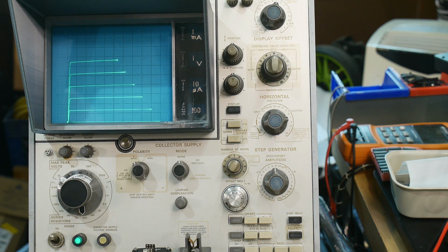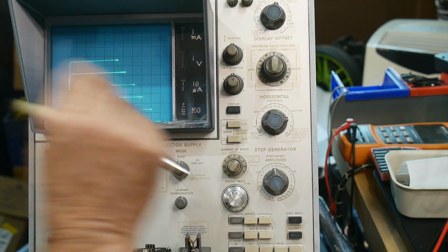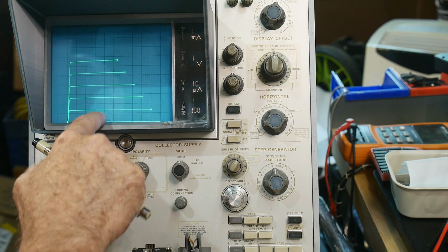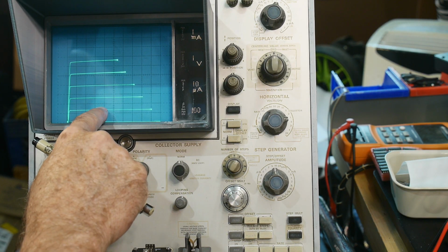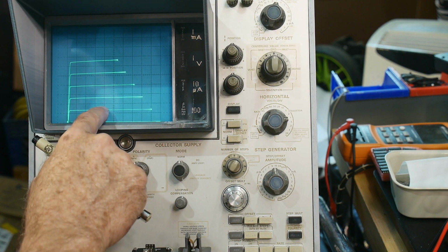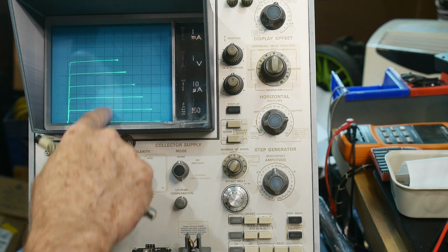Now, when you're using a transistor, what are you doing? You're using it like an amplifier, and so you're changing the base current. Your input signal is changing the base current. What is changing the base current? That's these families, right? So this is a little bit of base current. This was 10 microamps, 20 microamps. So let's say you wiggle up and down for 10, 20, and 30. Let's say you're wiggling up and down here, right?